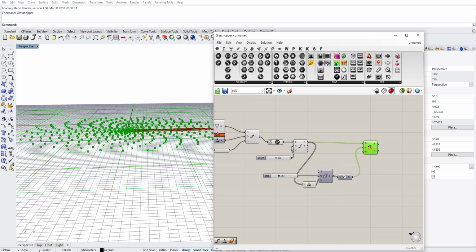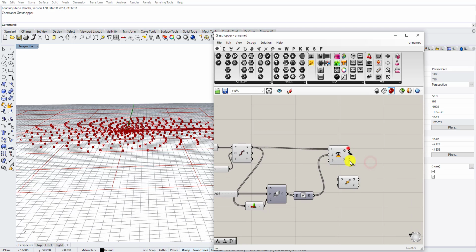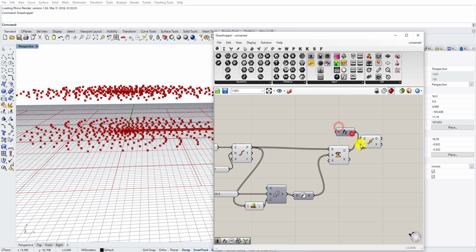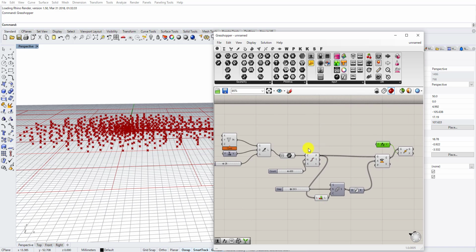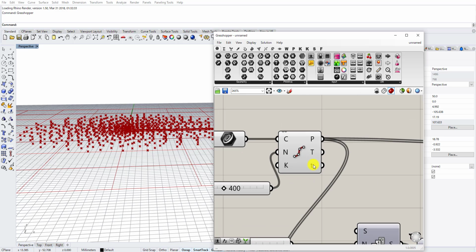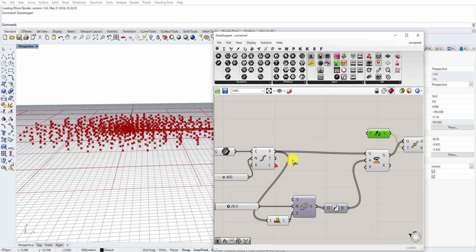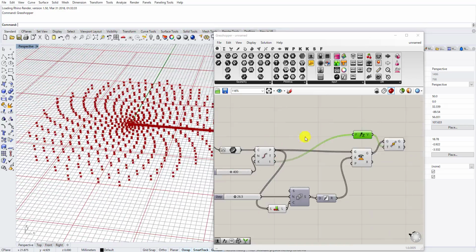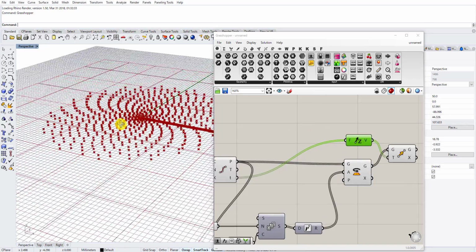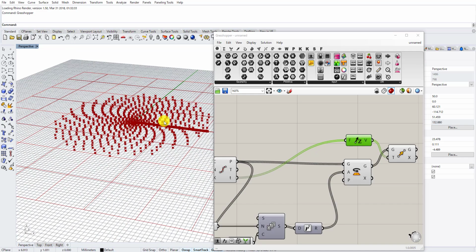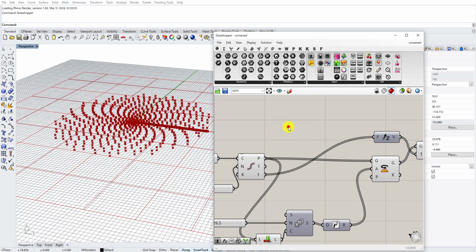Okay, now I also want to make it going upward so that I could make a rose like mountain. So in order to do that, I am gonna move each point in the z direction, and for the z value I can use this value t here, and I can just connect it directly, but it's just going linearly upwards, so I don't want that to happen.